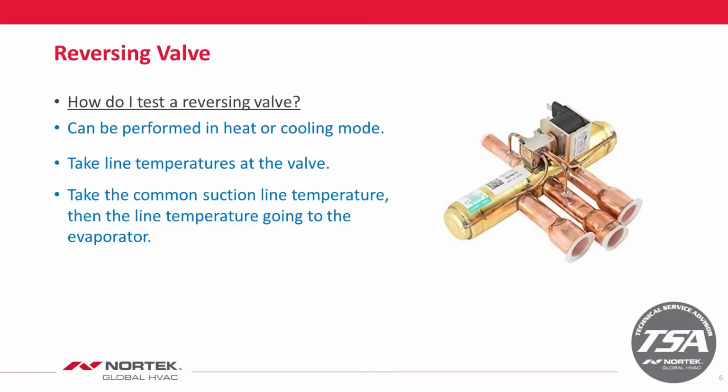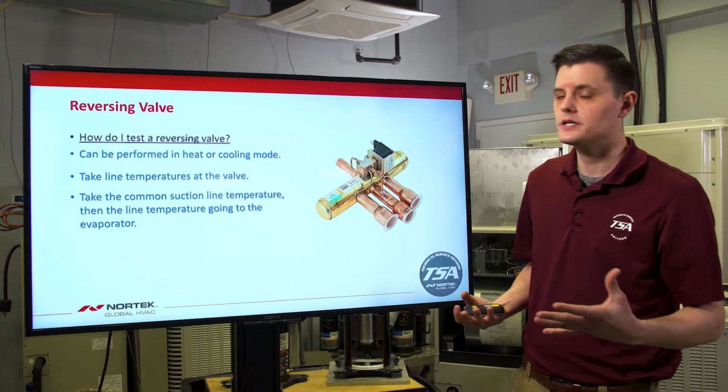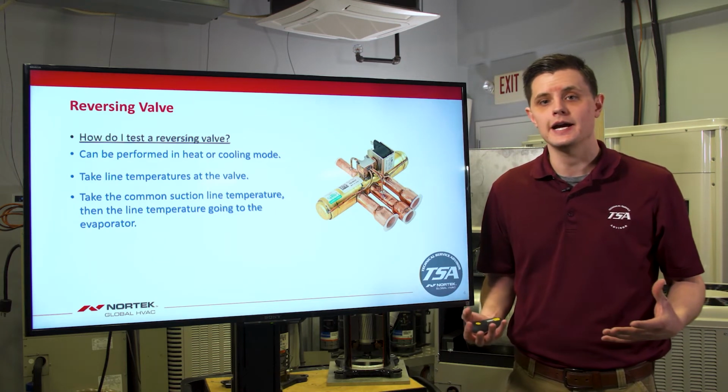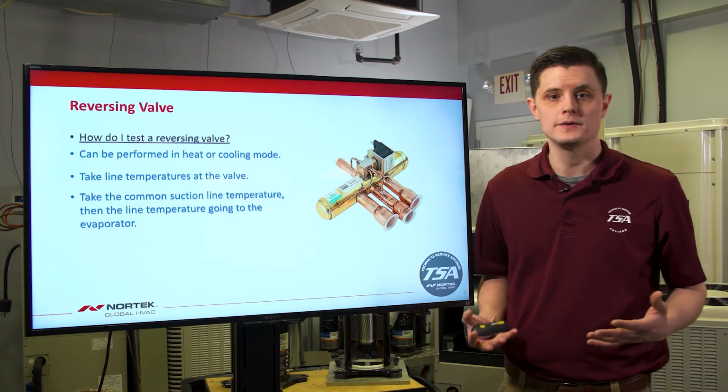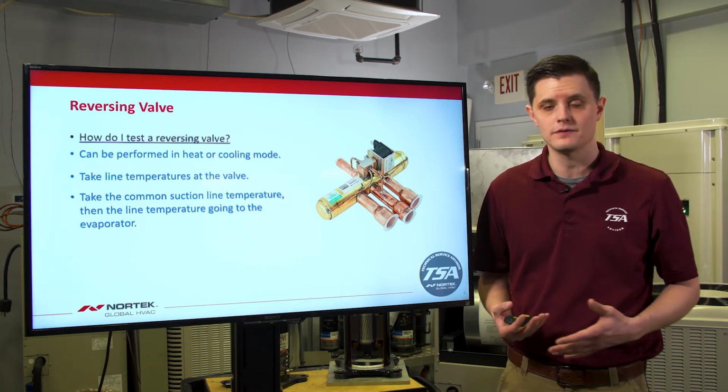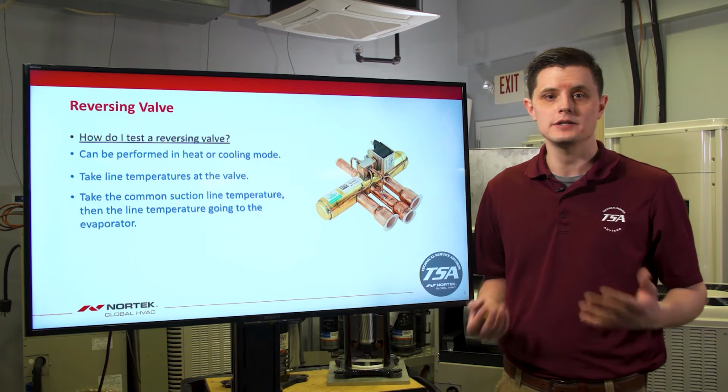Now, how do we test a reversing valve in the field? This can be performed in heating or in cooling mode, so no matter whether it's summertime or wintertime, you can do it either way. Basically, you're going to take line temperatures right at the reversing valve. So you want to use a thermocouple type thermistor versus a laser, for example, to actually take these